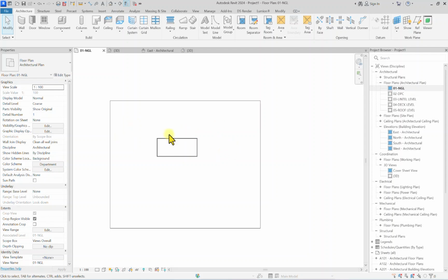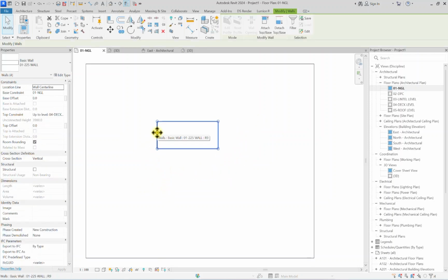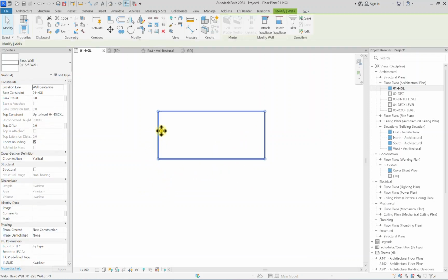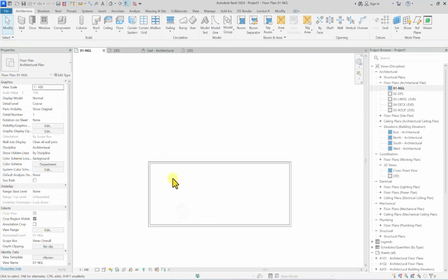So now I can also adjust the position of this wall. After I've created it, it doesn't mean it's permanently like this. So I can left click and select these walls here. Once the mouse icon changes from the normal one to this one that has 4 corners, you just left click, hold and drag it. So you can drag it to center. You see, left click, hold, you can drag it anywhere. So I've dragged it here. So now we have drawn this box.